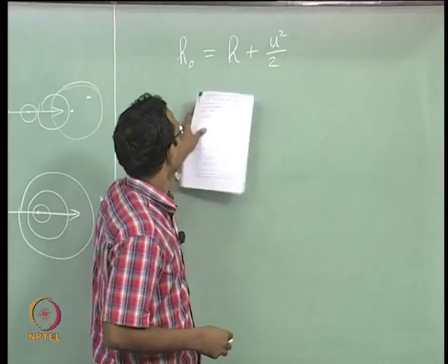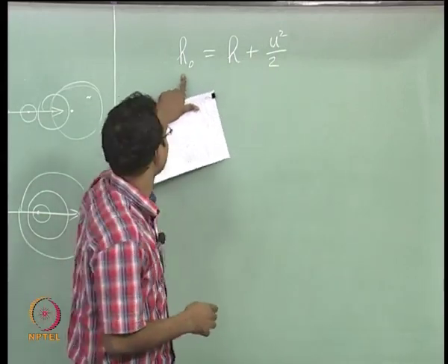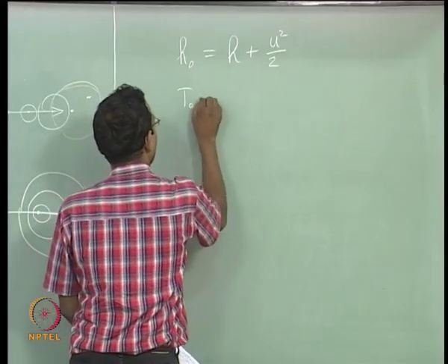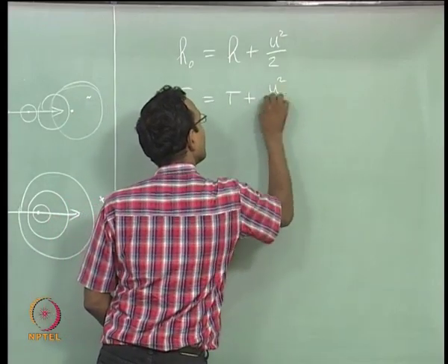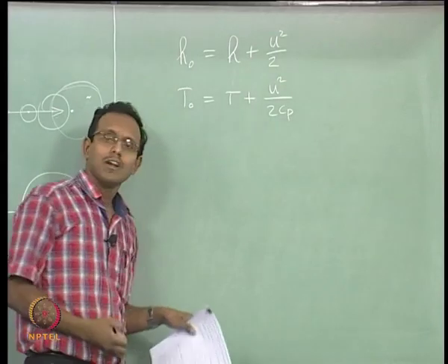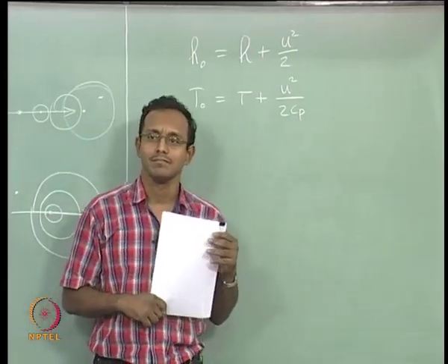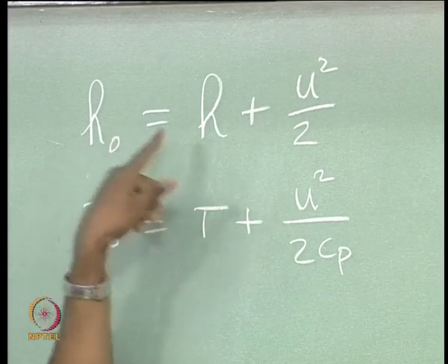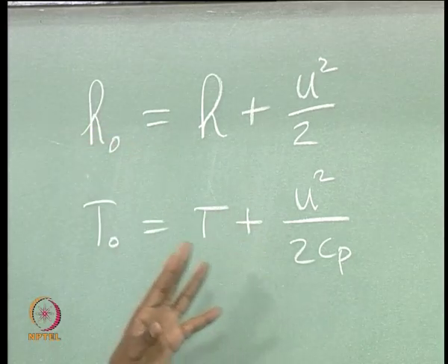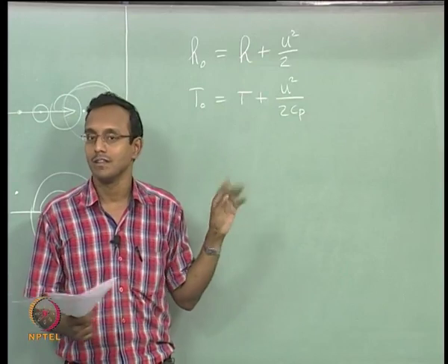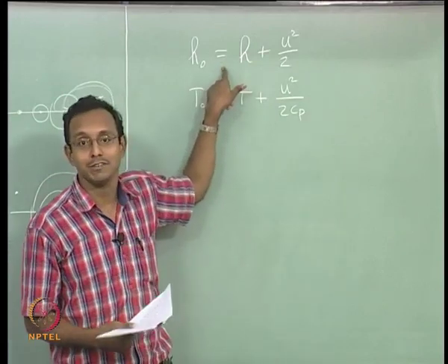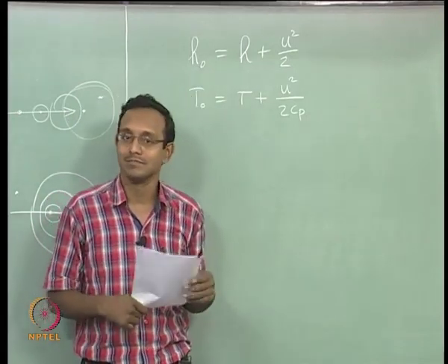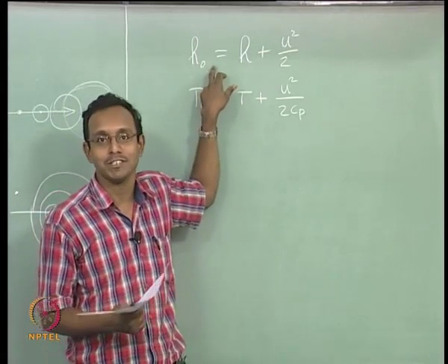So from here we defined this to be stagnation enthalpy, and now I am going to say if I have a calorically perfect gas, then I can write this. What if it is not a calorically perfect gas? Then the Cp here may not be the same as Cp here. So I have to keep Cp naught and Cp separately and calculate them independently; it is not going to simplify to this form, that is all. But that expression is definitely your energy equation, assuming it is adiabatic, steady flow, no heat transfer from anywhere else and all those other things. This equation is for one special set of assumptions, remember that always.